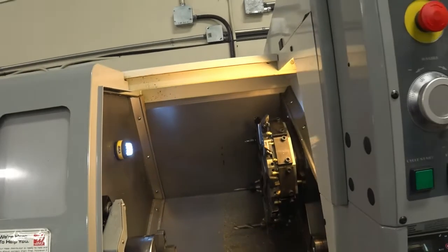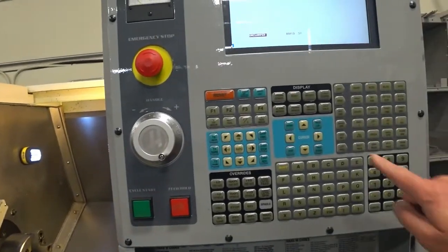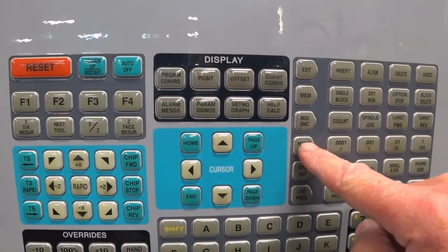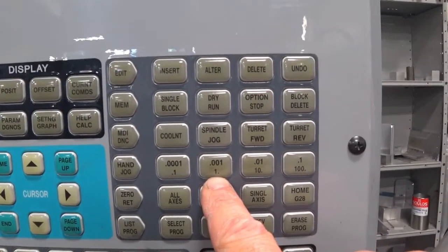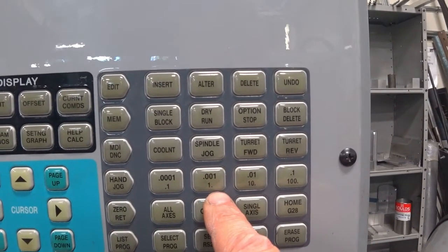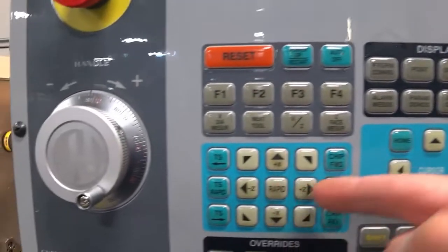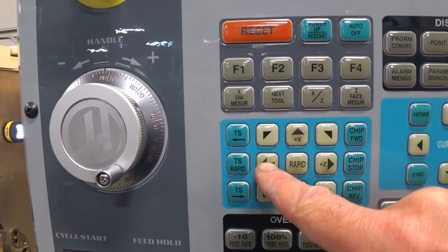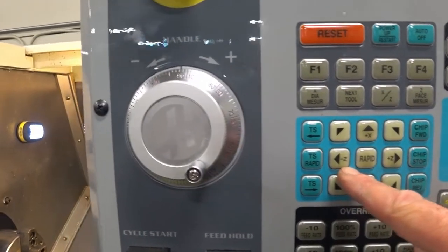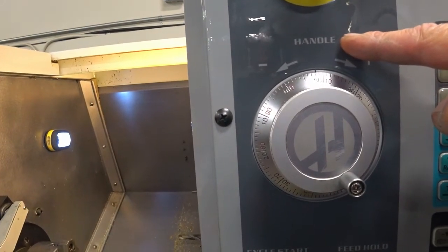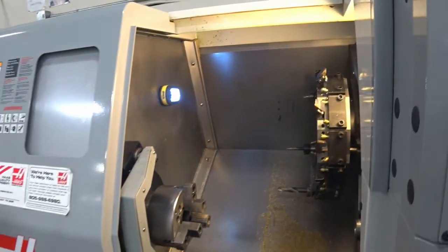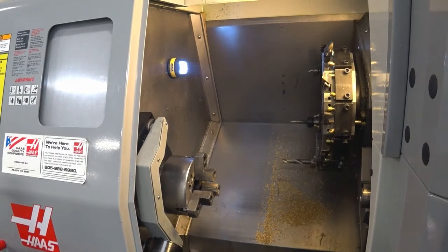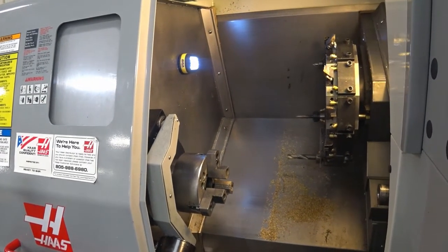Switching to hand jog mode to allow us to move the tool as we rotate the hand jog wheel. Selecting the movement scale to control the distance moved per hand jog wheel division is done using the hand jog feed rate buttons. Using the hand jog axis buttons to select the desired axis to move when turning the hand wheel. Note the plus and minus values and rotation direction arrows directly above the wheel. Rotation of the wheel will result in movement at a rate selected by the hand jog feed rate buttons, permitting accurate positioning of the cutting tool.